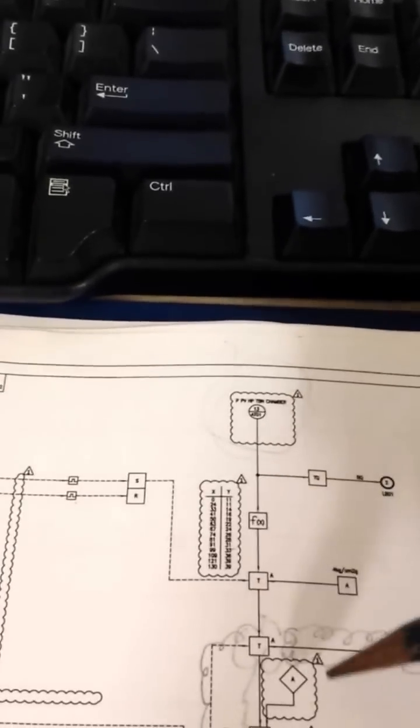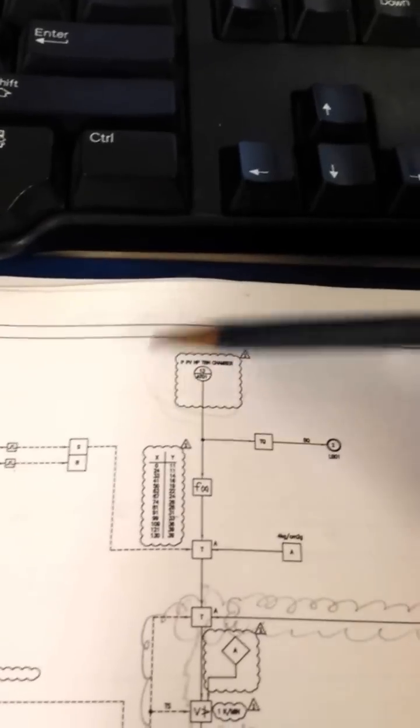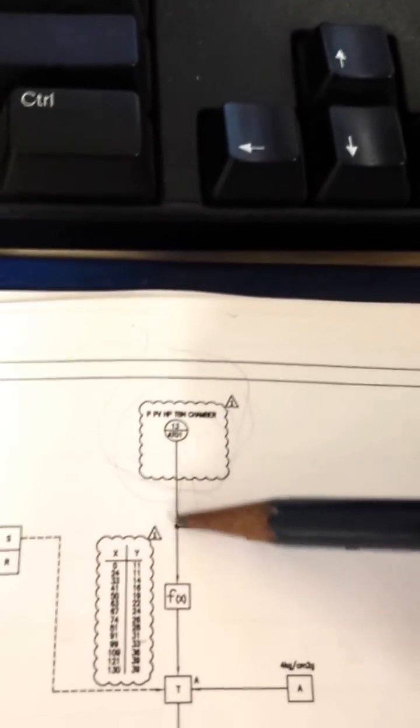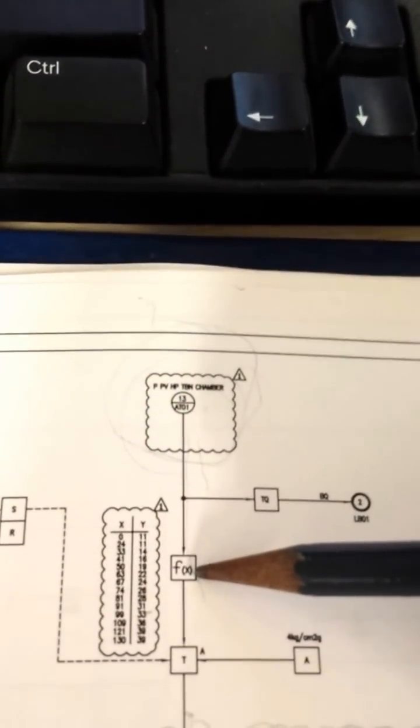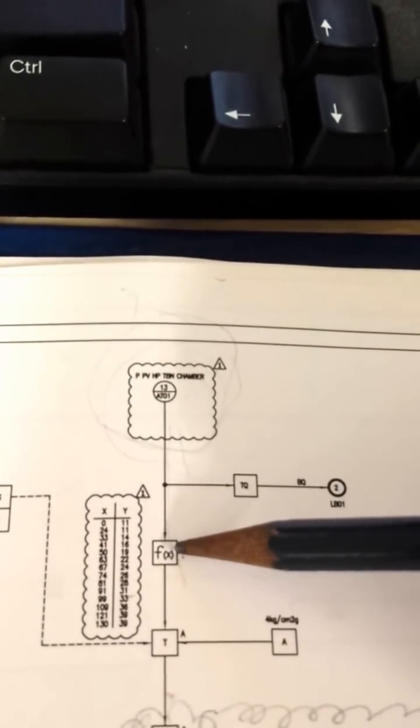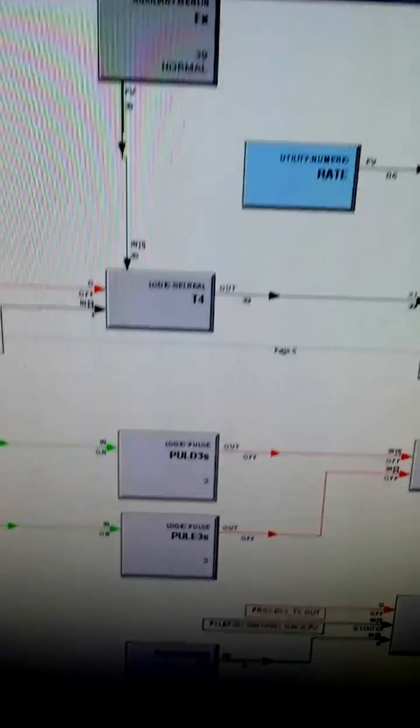Now we can say that the set point is cascaded from the other line. Cascaded. Okay, so from here the actual value of this transmitter is first passed through the function block. It is an f(x) function. The output of this is a function of the input. Let's see if it is the same in here.